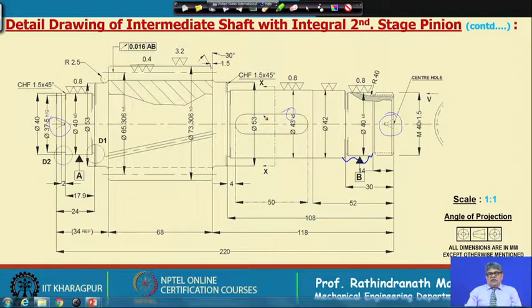And in dimensioning there are two ways. One is that you simply put that number, because that chart is available, the manufacturing engineer can dictate, or even a machine man knows what the tolerance will be. Alternatively you can put the plus minus value there itself.